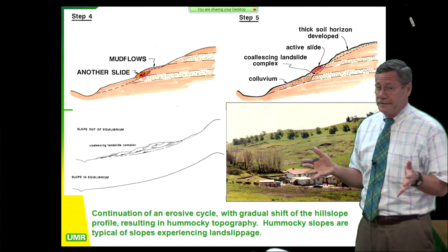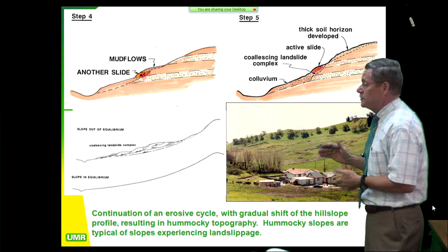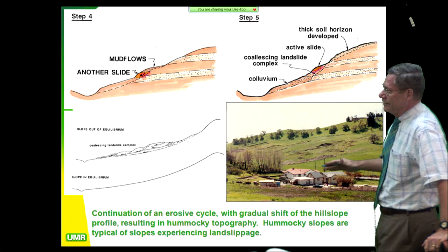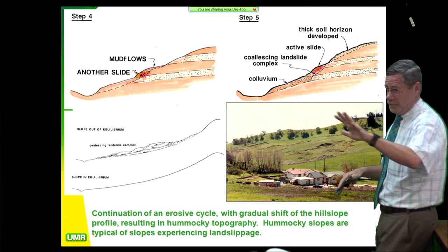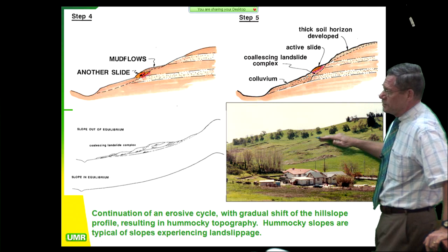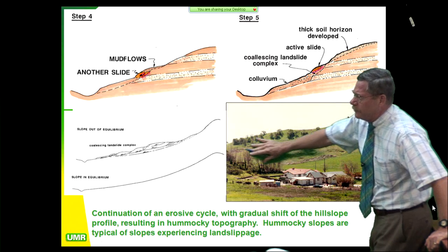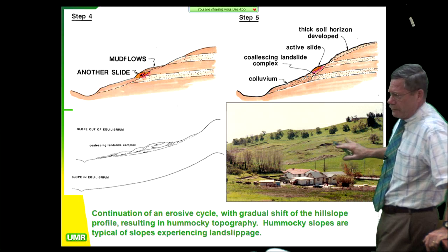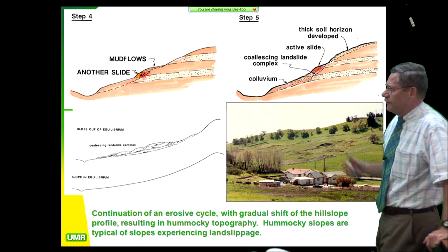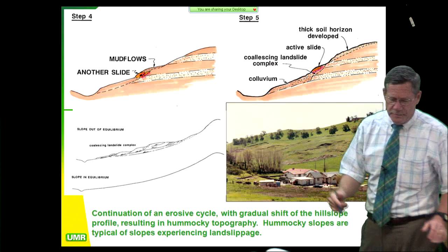You got to learn to recognize a dispersive clay when you see one, because if you try to handle a dispersive clay like a regular clay, you're going to get a lot of trouble. So you get a clay mineralogy class, you're going to practice soil mechanics, take one. Get at least one under your belt. Dispersive clay, bad news. So this has all been graded off and repaired. See how well the repair worked? It didn't work worth a darn. It worked for about 9 years. And then this whole thing started failing because the subdrains clogged up.